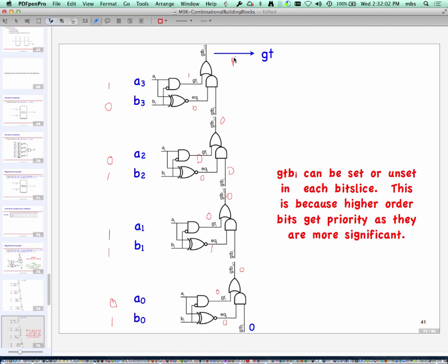And so you have to ponder over this logic, but it's the opposite of my decimal example where we were starting from the top. You could design a comparator that way also. You can design a comparator which starts by looking at the top bit and then walks downwards. Now, in the homework, in the design problem, you have to compare the set point and the 10. And you could do it this way, or because there the number is so tiny, there's 3 bits each, you can just directly do it as a sum of product of sums.